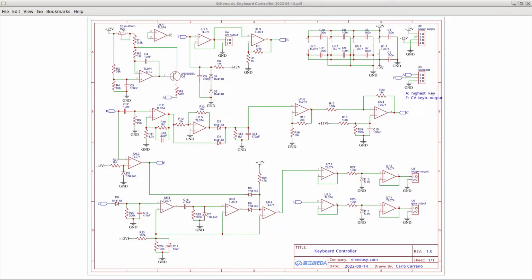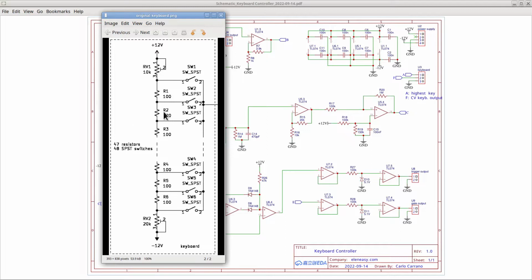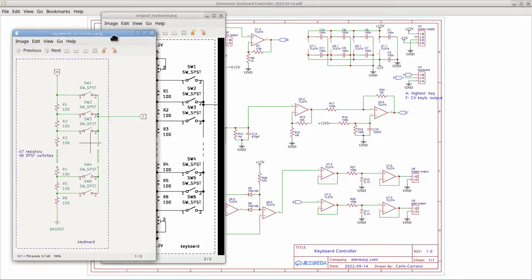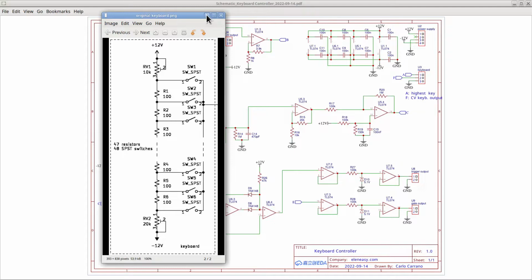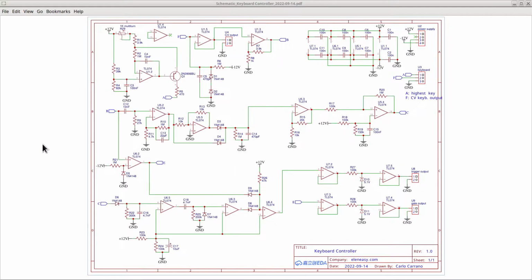In the case of the constant voltage, if I press 2 keys, I short 2 resistors together, making unpredictable the output control voltage while playing. The result is that strange sounds may be generated. In the case of the constant current, it doesn't matter how many keys I press. The final result will depend always on the lowest key being pressed, and other keys will have no effect. This is actually the solution adopted in the first analog monophonic synthesizers. The CV output only depended on the lowest key being pressed, and that's what we really want to reasonably play a melody with a keyboard.